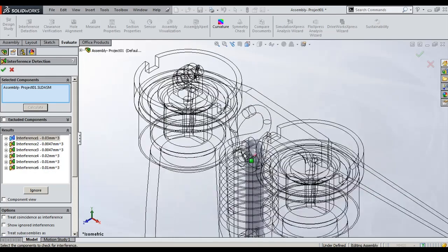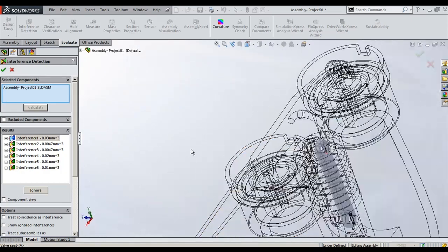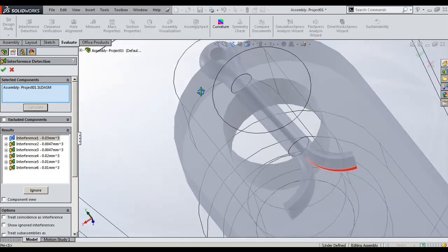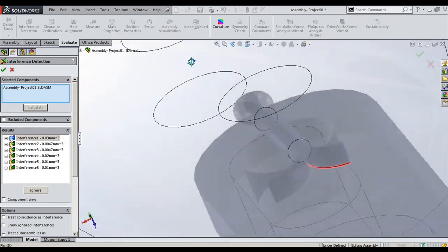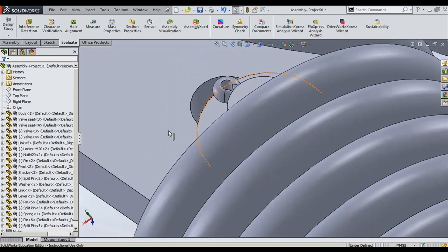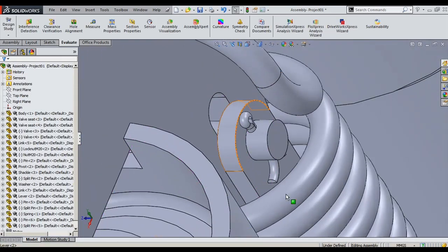So now your job is to understand where the issue is and what we need to do to avoid this. Now one basic thing I would like to show here. Here you can see the split pin is not properly located, so it is having a slight interference with the base link. Now I will go and manipulate it so that the interference will not be shown here.